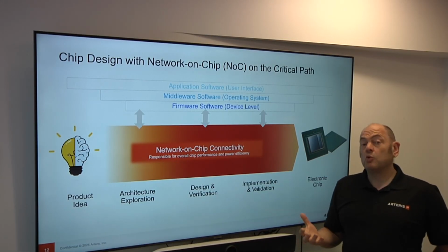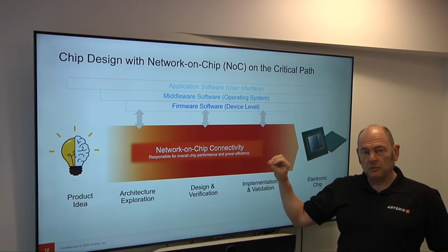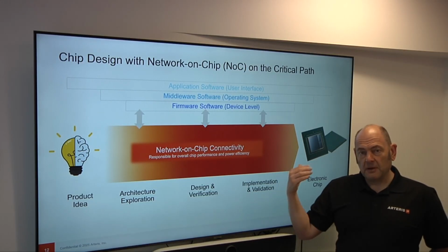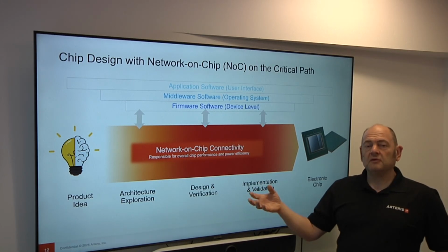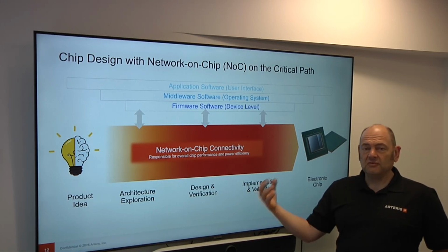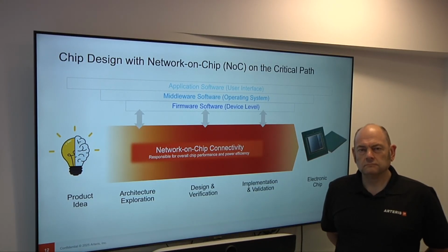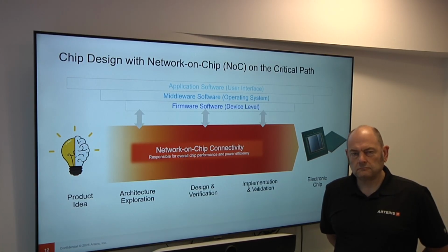So we need some level of quality of service that is actually managed through the network interconnects, and we set that up to ensure that the quality of service gives the right bandwidth for the devices that need it, the IPs that need it, and it also deals with the latency, such as updating the screen in a timely manner. We also have a lot of MAC elements that are operating in an AI chip. Those can be accelerators or GPUs or anything else. It's still the same problem of you have a lot of processes going simultaneously. You want that data to end up in exactly the right place at the right time.